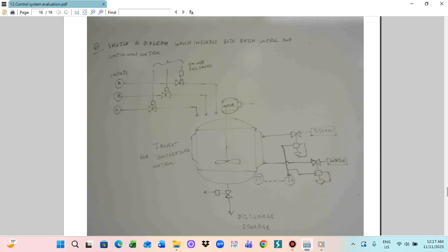The C, controller function block. Which one is the controller function block? In this case, the controller function block is the FE13. So this is FE13, the main controller. FE13 is the main controller: PID, proportional, integral, and derivative control.